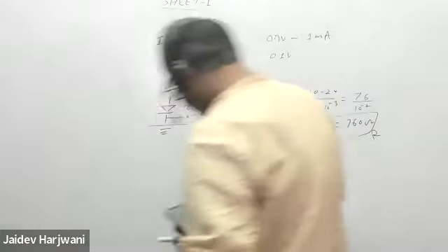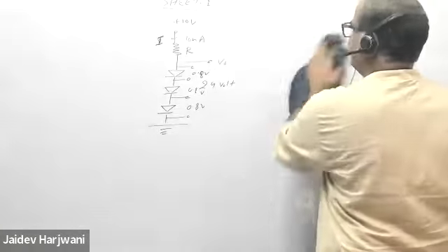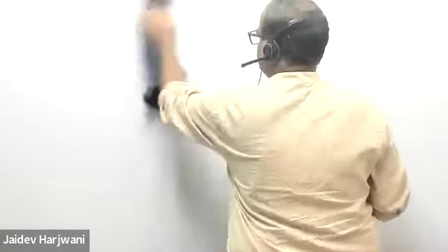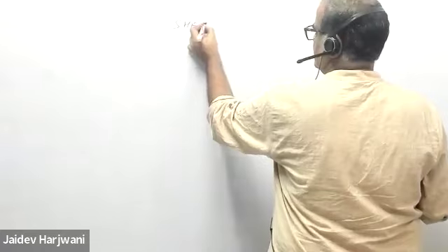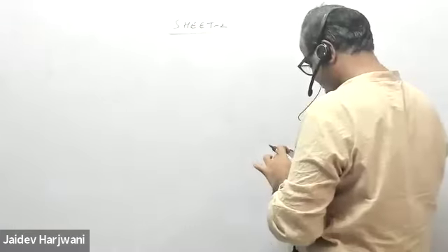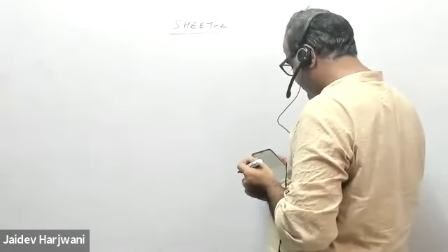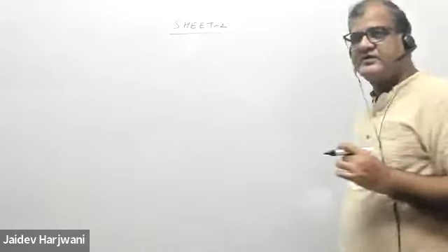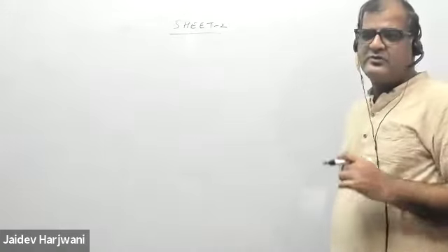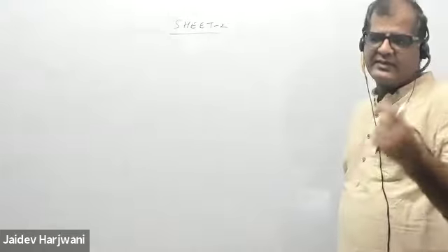Now the next question is again on Zener diode. Say a Zener diode whose nominal voltage is 10 volt at 10 milliamps has an incremental resistance of 50 ohm. Okay, so this is the example. Like we have discussed in the class, the piecewise linear model. In the piecewise linear model, you say the diode has some voltage drop plus it has some resistance.